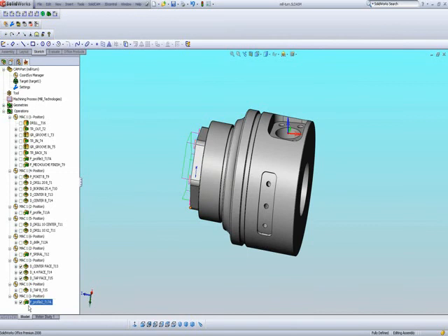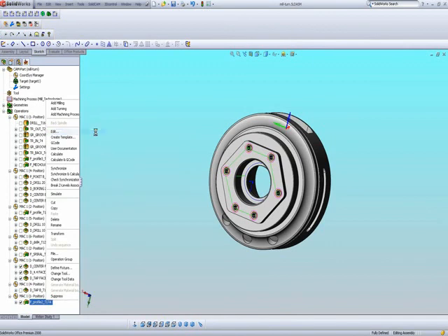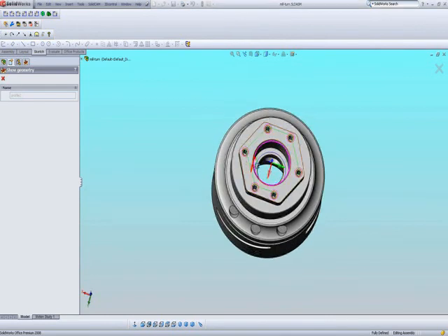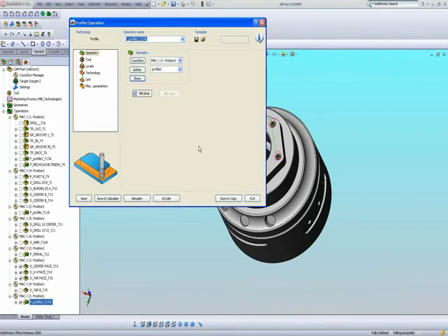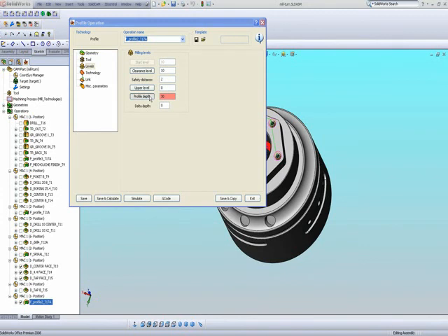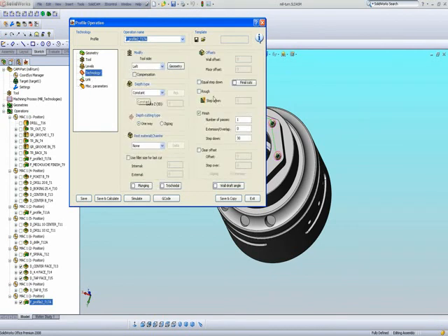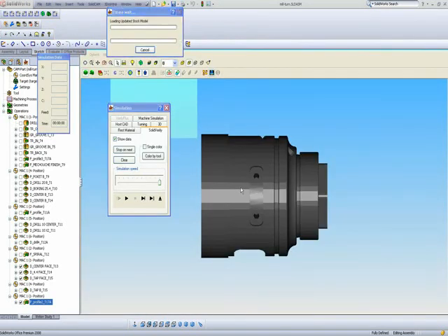And I have the same thing with my last operation. What I'll be doing is showing that this area over here, I'm going to just do a simple milling operation also. Notice I didn't have to do it by turning. I can also do it with a milling operation using a regular end mill, my levels, going down to this level over here, my technology, finish cut.